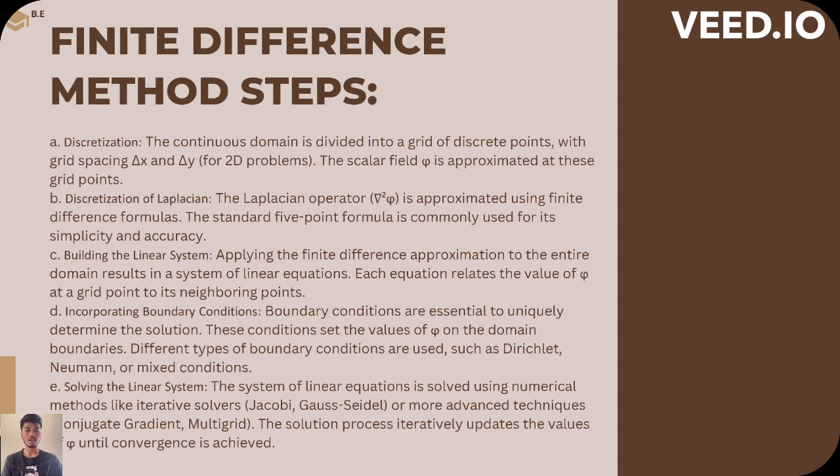Lastly, solving the linear system. The system of linear equations is solved using numerical methods like iterative solvers, as I mentioned, Jacobi, Gauss-Seidel, or more advanced techniques like conjugate gradient, multigrid. The solution process iteratively updates the values of phi until convergence is achieved.